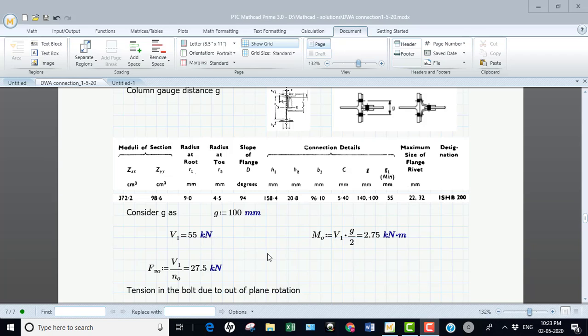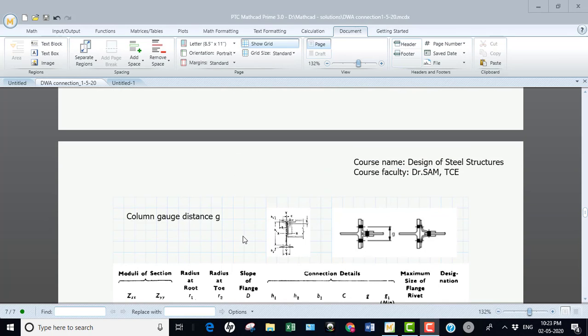See here, this is the bolt group I am presently discussing. At this juncture, the shear force is expected to transfer. Though the load is shared along this plane, the CG of the load is expected here. Therefore, this group is also subjected to an eccentric load. So this will be the eccentricity. To calculate the eccentricity for this bolt group, it is nothing but this distance divided by 2.